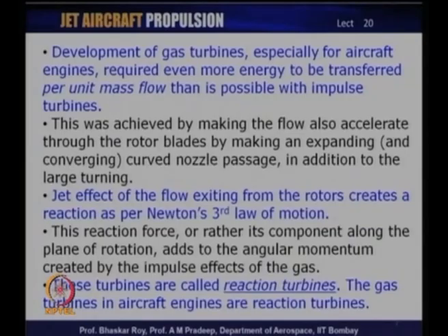Let us quickly summarize what is happening here. The development of gas turbines, especially aircraft gas turbines, requires very large energy transfer through the rotor per unit mass flow. Now, this is normally a requirement for aircraft gas turbines, and this is much more than what a typical impulse turbine can do. Which means that the requirement of an aircraft gas turbine is more than what a normal impulse turbine would be able to do with the same gas.